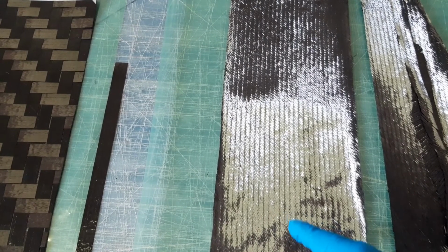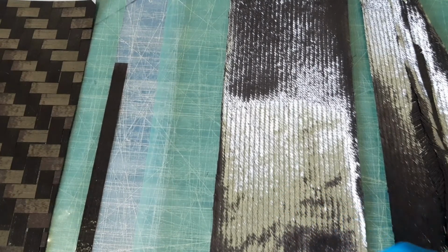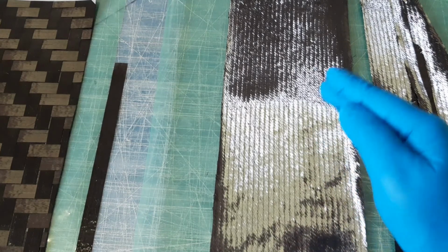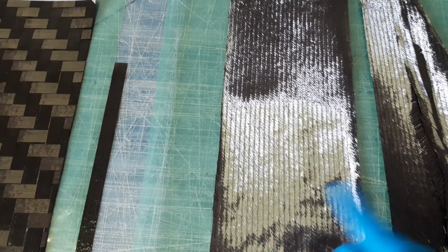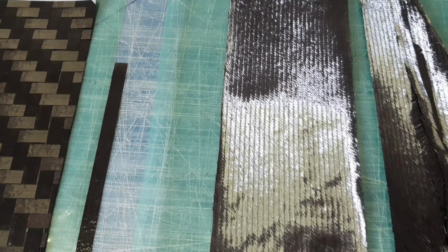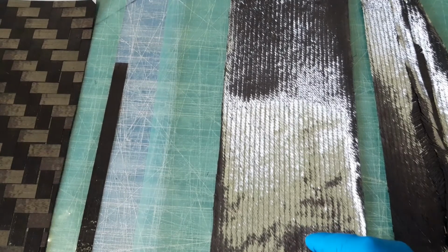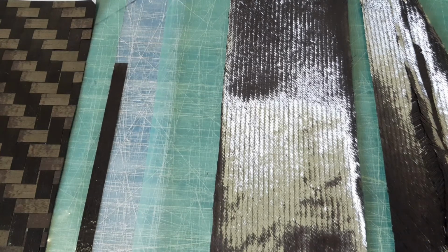And this will be stronger, will be tougher than material which is just plain laid up, one axis in this direction without any stitching, another axis in this direction without any stitching. So basically, if it is plus minus 30 degrees and it is made from uniaxial tapes, like some of the bicycles are made, they will have less toughness compared to this. But there, basically, toughness is not important. It is the strength that is important. In strength, they will be exactly the same. But in airplanes, toughness is very important, and that's why this is a better material for our application.